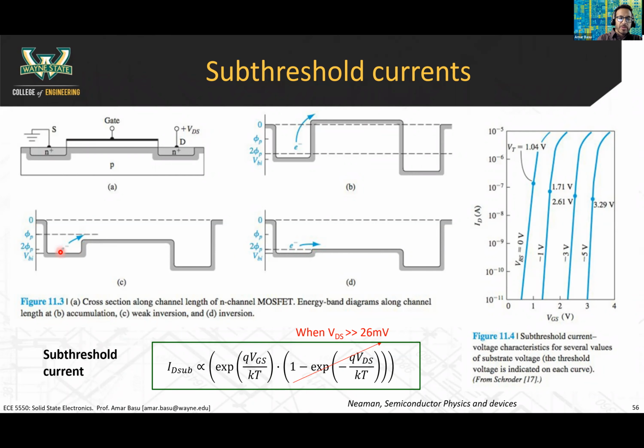Remember, this is the source, this is the channel, and this is the drain. There's a barrier that prevents electrons from going up into the channel region and then into the drain. At weak inversion, that barrier height has gone down to the point where some high energy electrons can get through and go on into the drain. At strong inversion, that barrier height has become even smaller, and now most of the electrons can go through into the drain. The point is, even at weak inversion, you can still have some electrons that make it through.